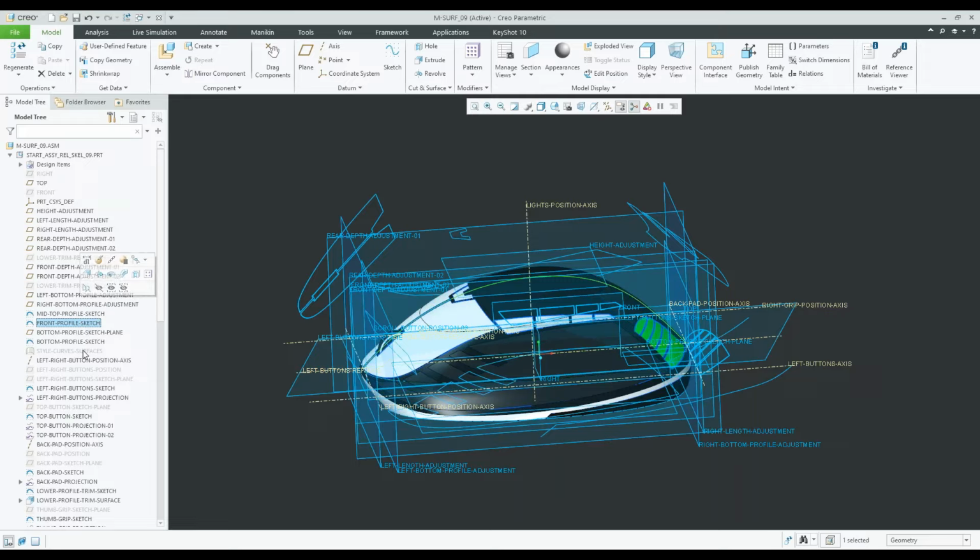So if I activate the skeleton part, right, you can see that once that part is activated, at the very top right, we see style, and that's the ISDX feature, right? So I just selected that, and we'll go into the feature right now. It's hidden, but let's select it, edit definition, right?